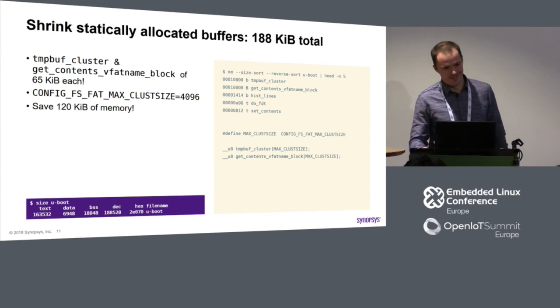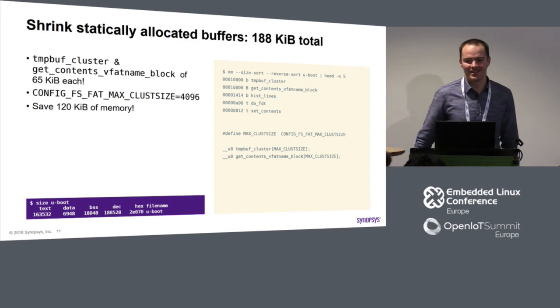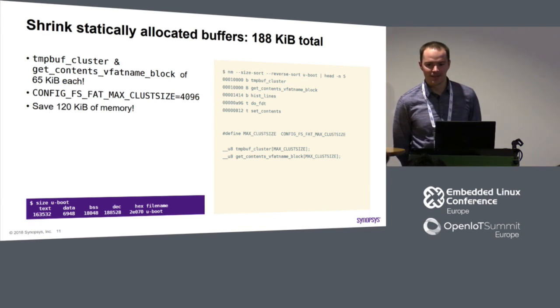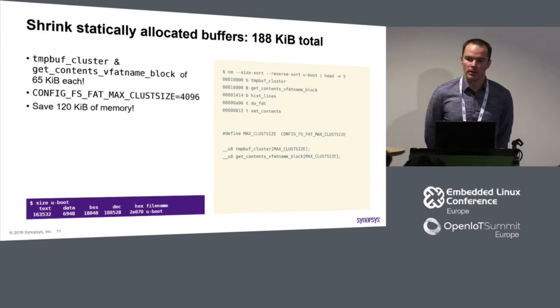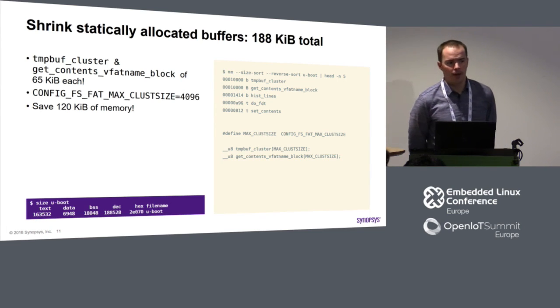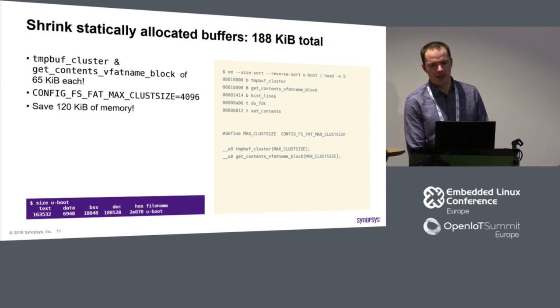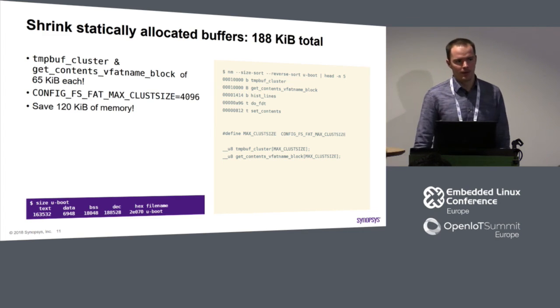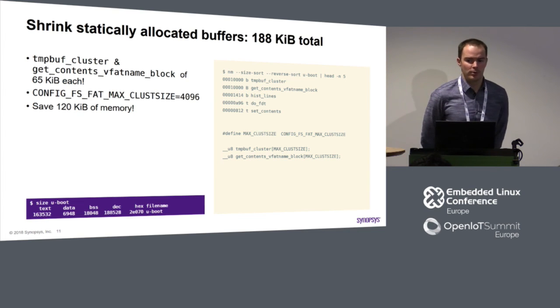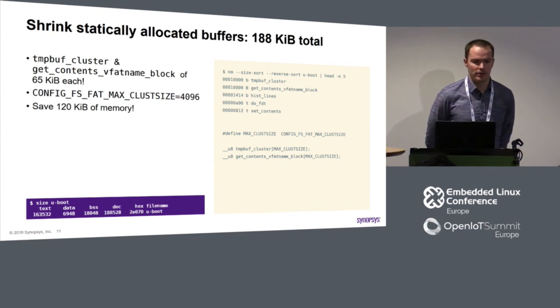Well, actually, there are systems that have SRAM limitations, and you need to load U-boot into that and execute it. But for that case, we have SPL, we have all those tricks which will strip down all the printfs and all that. That is what I would use in that situation, that's for sure.